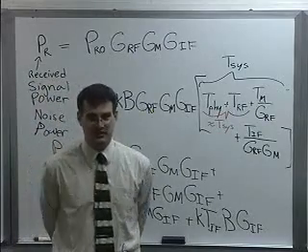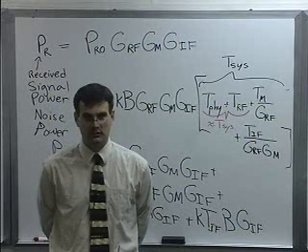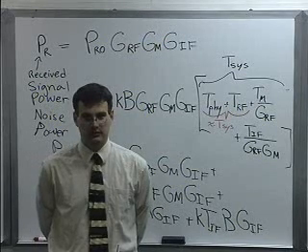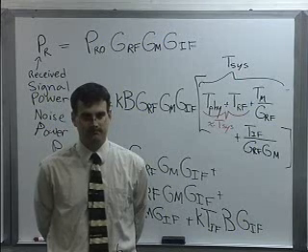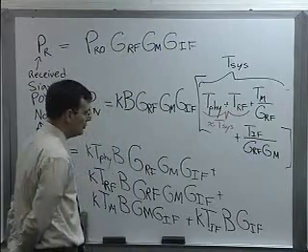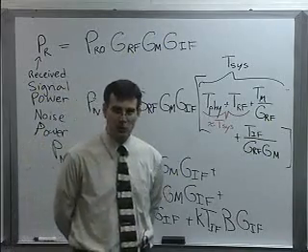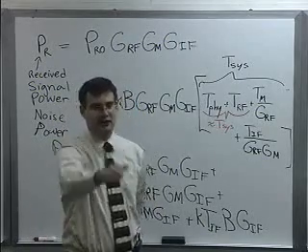Yeah, you have a question? Talking about that, is it a good idea to have a band-pass filter after the LNA, because a band-pass filter will have some loss, and so that will increase your overall noise figure of the system? There are some instances where you may want a bandpass filter after your LNA. And I forget, what is your name?